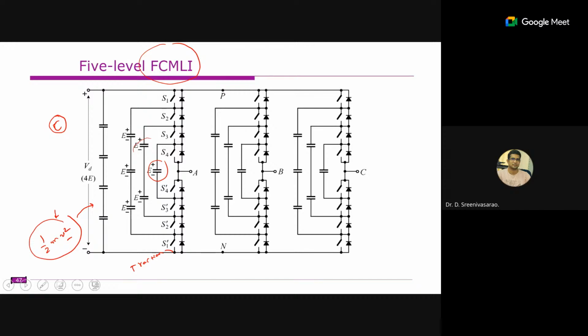Right. So why do we need to do this quickly? For example, if the velocity is reduced by half, that means you have already lost 75% of the kinetic energy, right? So you must be quick. These capacitors or ultracapacitors quickly store the energy, and they will gradually release it to other things like batteries or some other places. That's why it is especially useful for traction applications where we have frequent stoppages. For that, we can use this one.